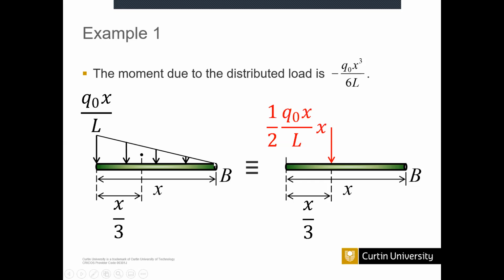At this point, it is 0. So you know how to find the area of the triangle. You know this length and this length. Then you multiply those two and multiply by half. This is the area of this triangle that represents the total load carried on this column. Are we clear?